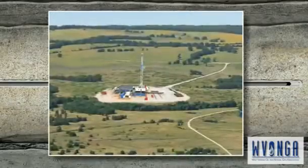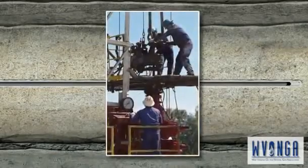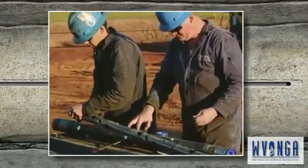At this point, the drilling rig is no longer needed. A temporary wellhead is installed and the location is prepared for the service crew who will perf, frack, and prepare the well for production. The first of these steps is to perf, or perforate, the casing.